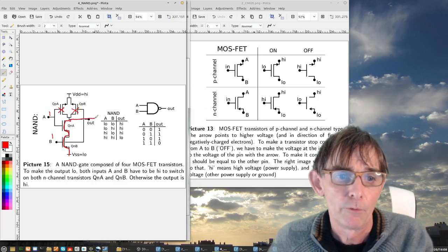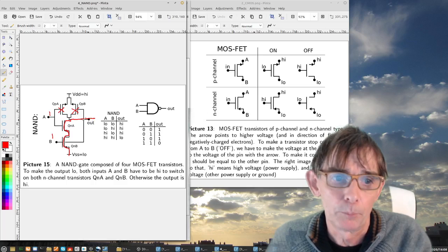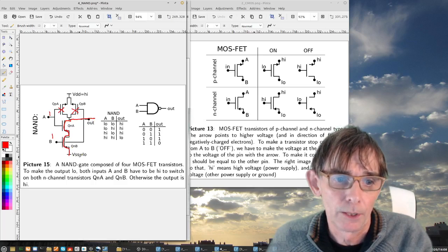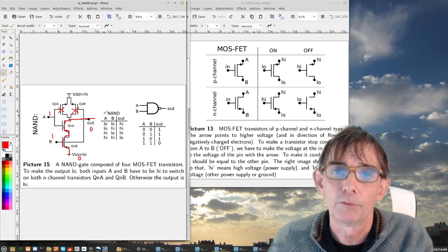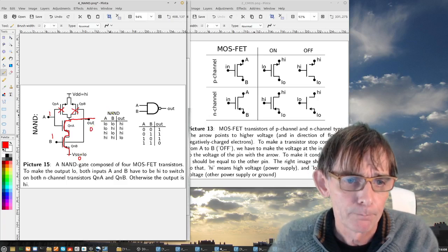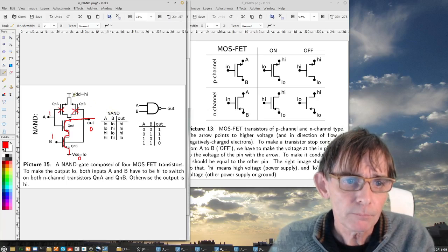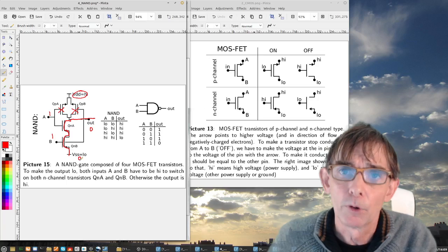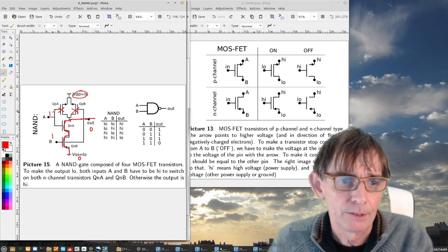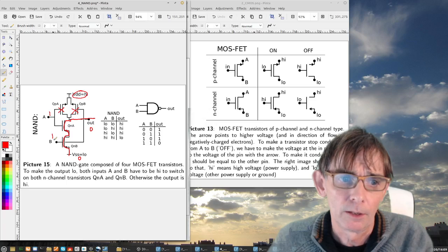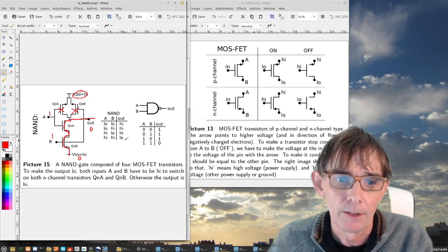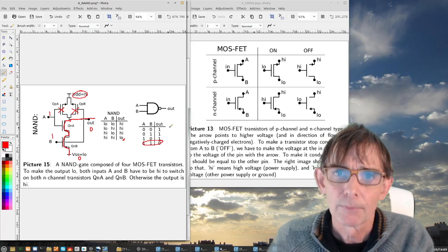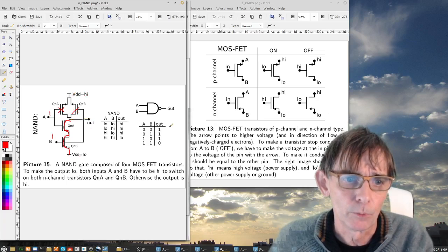So what do we have? We have a path from the output short circuit to ground to logic 0, and the 0 of the power supply appears at the output. And again, we don't have a short circuit from the positive power supply to the negative, to the low power supply. But anyway, in this case that you put logic 1 on both inputs, or 2 times high, the output is low, is a logic 0, as you can see. This is then how a NAND gate works.